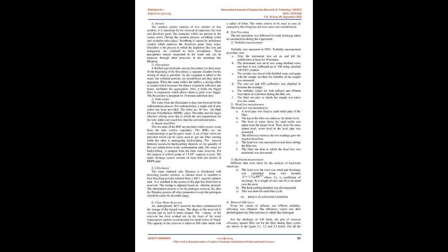The flow of water is reversed so that the treated water flows backwards through the filter. During this process, the sand is resuspended and the solid particles are suspended in the surface water. Generally, the air is used for agitation and further aids the cleaning process. The filter is again put back to its original operation when most of the particles are washed out and backflowing water is clear.